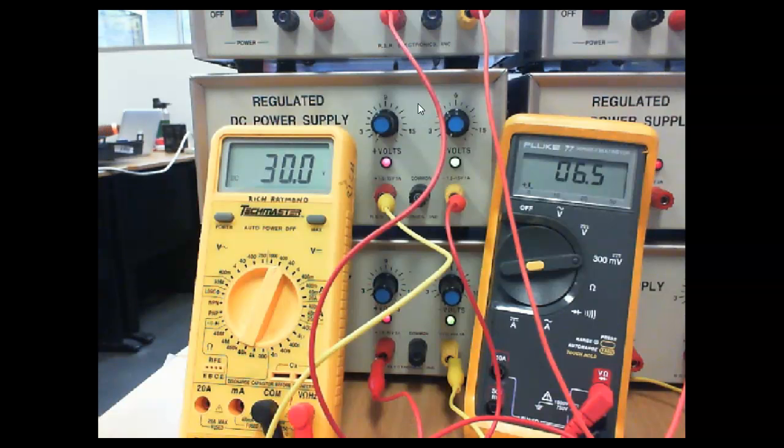Well, what we're trying to do is the voltages are given, so instead of using the ones they do, I knew the diode never breaks over, so that's why we're going 30, 60, and then we're not going to do 90, we're going to go until it breaks over. So what we're doing is we're trying to figure out where it actually breaks over at. So the two things where it breaks over is, of course, the voltage drop that we put across it, and then the current that we put through it. So what's 6.5 divided by 1 million?